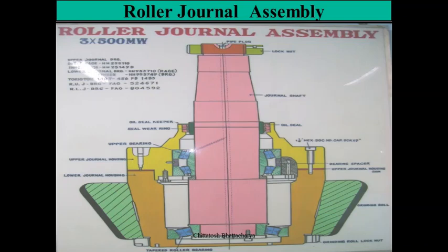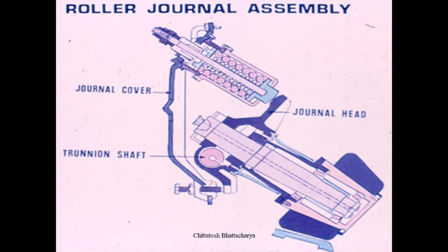So this way we see there is continuous recirculation of coal particles within the milling system, and finer coal particles go through the coal carrier pipes. Now coal feeding is done in such a way that there is continuous drying, pulverizing and carrying of coal across the coal carrier pipe.